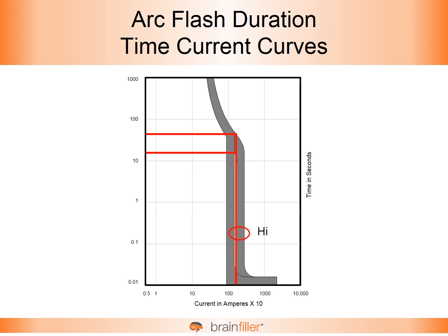A lot of people refer to it as the 2-second rule. But in any case, the concern about condition of maintenance and the device is that you're looking at time current characteristics to predict how long the arc flash may last. And unless the equipment is actually in good working condition and good condition of maintenance, you don't really know. The condition of maintenance is very important, and so that's why this article is introduced, to make sure that you have good condition of maintenance and that the devices operate as they should.